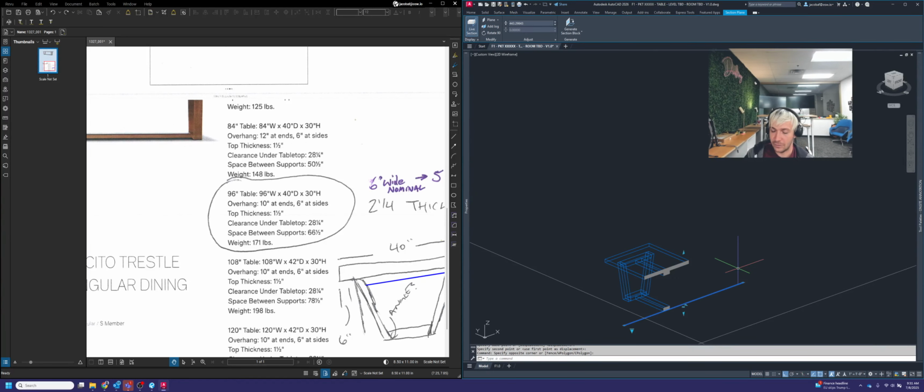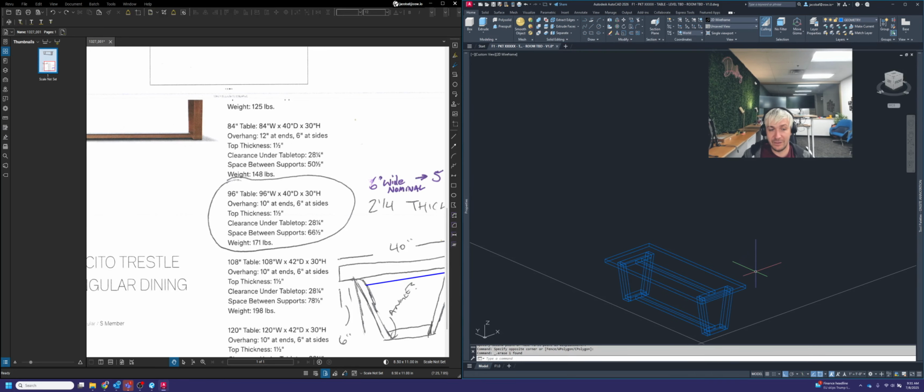I like to also delete that section plane once I'm done with it. So I can highlight that and delete it. I've had problems in the past, just to give you forewarning, that if you keep that on and don't delete it, there have been times, and this might just be a fluke, where I've been working on something and part of my model, when I go back into that CAD file later, is gone.